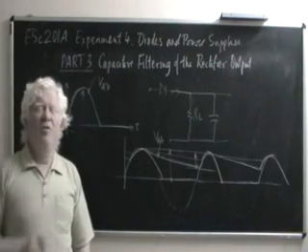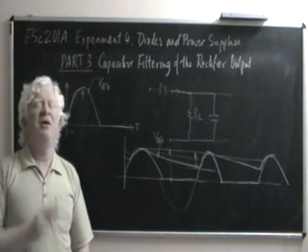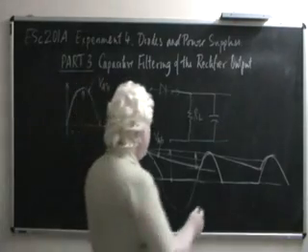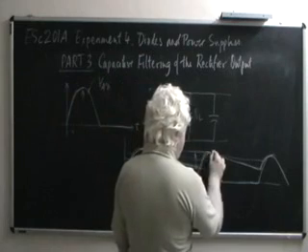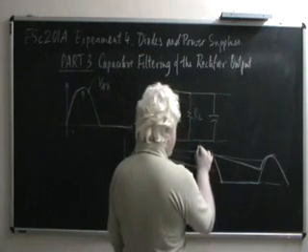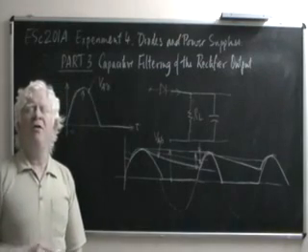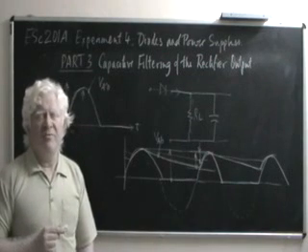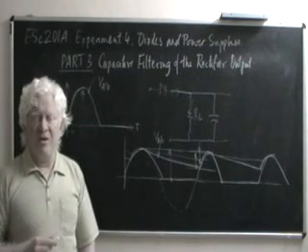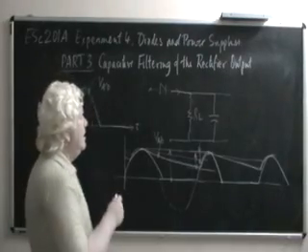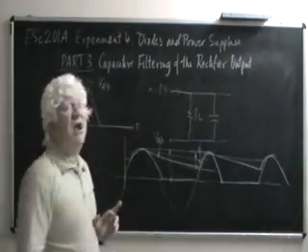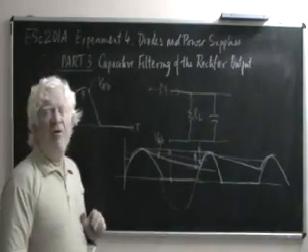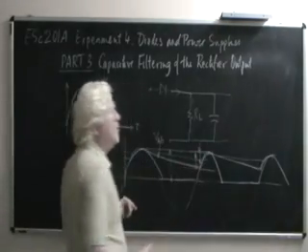At this stage, it is worthwhile to understand the advantage gained by using a full wave rectifier against a half wave rectifier. You see, the amount of peak to peak variation, I just said that this amount of variation depends upon R and C, or on the product of R and C, which is not incorrect. But it also depends on another thing. It depends upon the distance between the two times at which the capacitor gets an opportunity to charge. And in the case of a half wave rectifier, those two times are one cycle, one period apart.